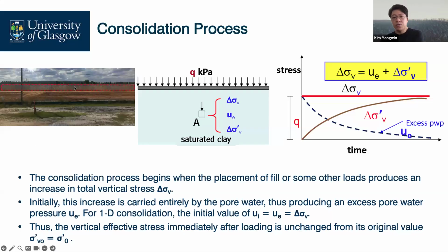This slide explains how consolidation is going on. The important thing is that the x-axis is time dependent. But for the calculation for NC clay and OC clay, we only focus on this. Today's topic is these things, this timing. How can you calculate 1 year, 2 years, 3 years, rather than the final settlement at 5 years?